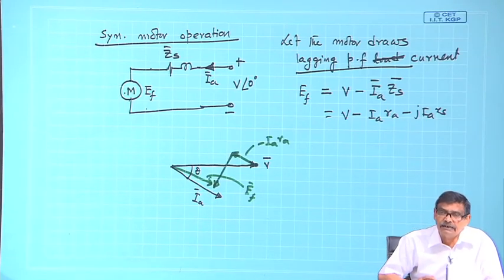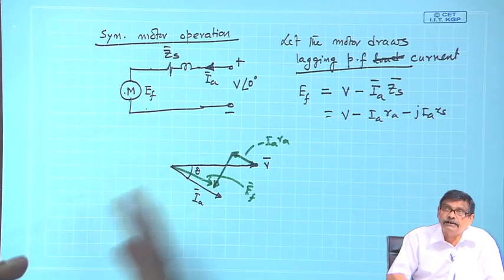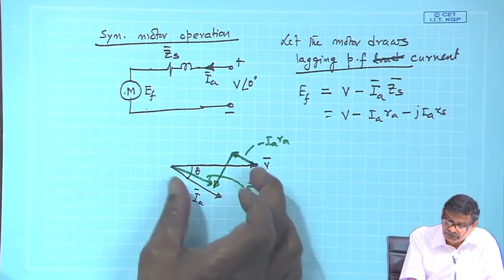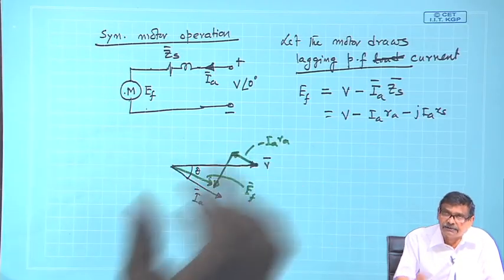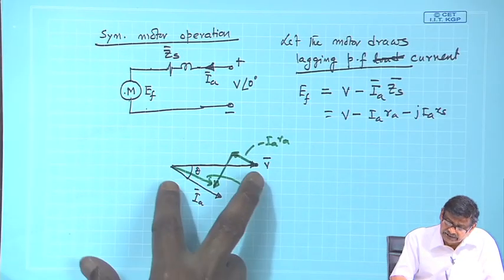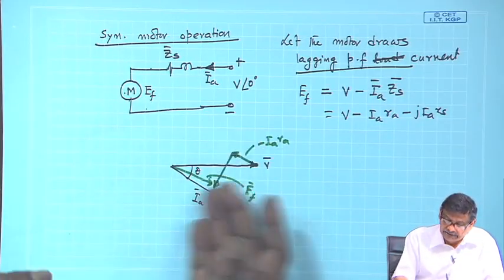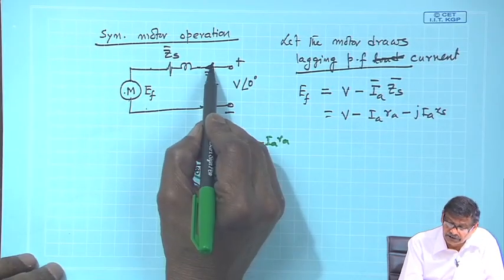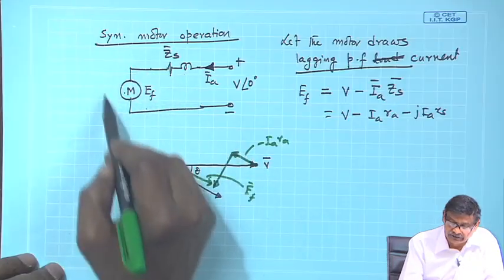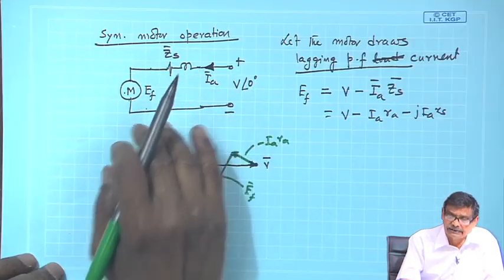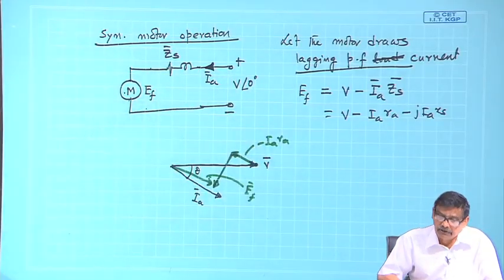Excitation EMF means the rotor field, this length denotes. V denotes the resultant field. Therefore, you can easily see the resultant field is more than E f and it will act as a motor. So, in motor mode of operation, it is essential to draw the Phasor diagram in this way, at least this is the convention I will follow.